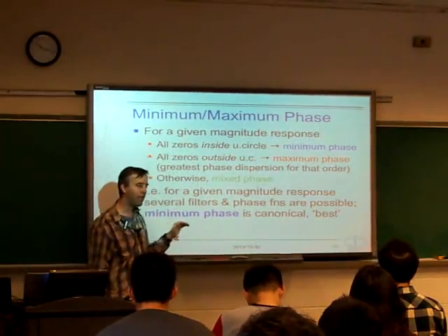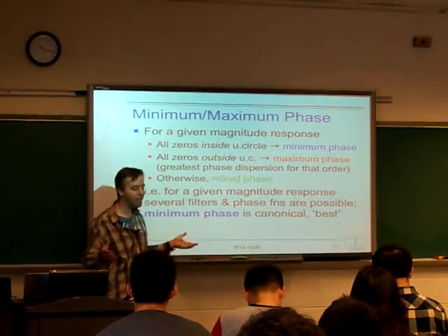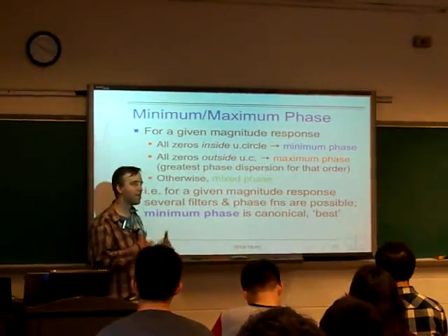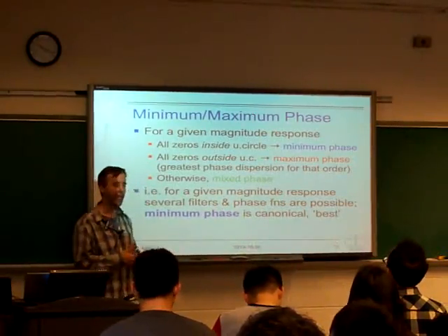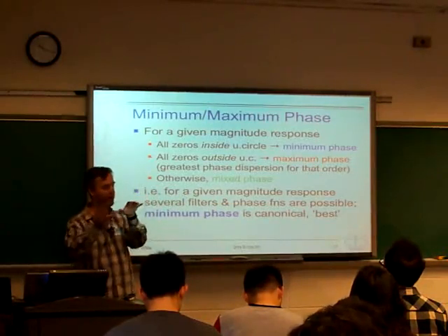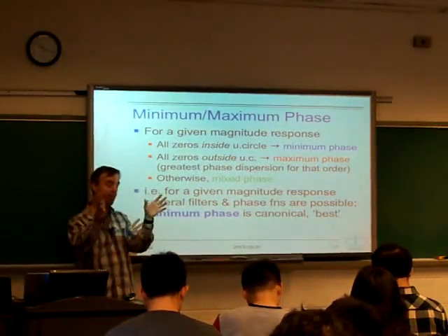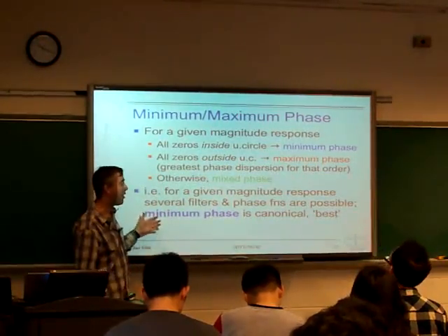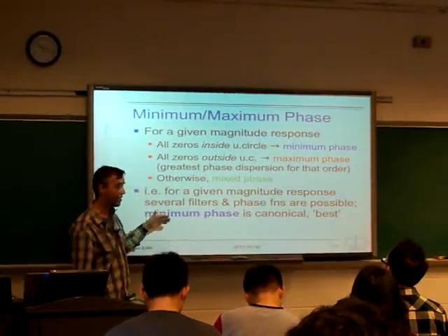Generally we don't like phase dispersion. It's modifying our signal in some somewhat difficult to characterize way. It's taking a complex waveform, breaking it down to sinusoids, and then moving them by different amounts. So now the shape of the waveform, when we add them back together, won't be the same. Generally speaking, we prefer the phase to stay as close to 0 as possible.